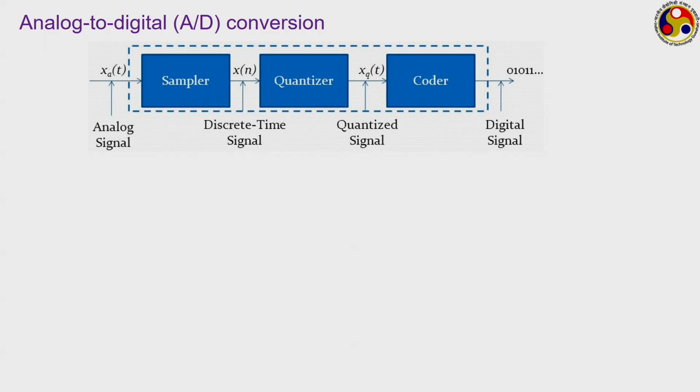In any analog to digital converting instrument, you will find there are generally 2 steps, or I should say there are 3 steps. First, there is a sampling step, where from the analog signal a specific number of data points are collected, which is called sampling. Thereby the continuous analog signal gets converted to a discrete signal, where a specified number of data points are available over a period of time. And then using that sampled data, we get a quantized signal which is produced by the quantizer.